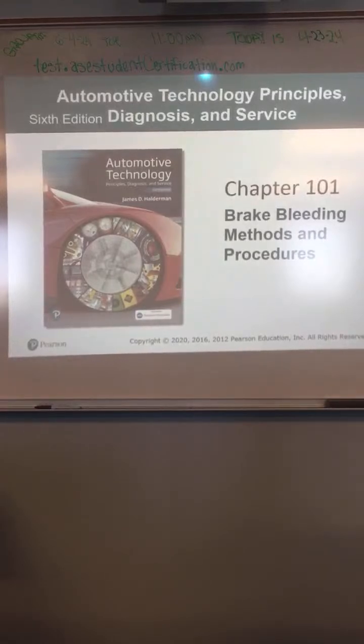Under what circumstances would you have to do a brake bleed? When you have brake problems, spongy. But under normal conditions, would you have to bleed your brakes when you replace the brake pads, the rotors, whatever? Would you have to bleed the brakes? No. You're not going to get any air in the system, right?